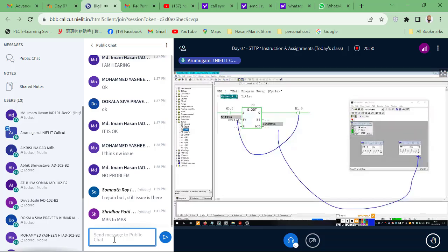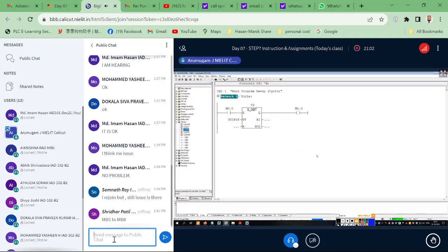We have to add one switch here. Here you see, assign a normally closed switch. That address is this address you have to assign. That's all. That means it will continuously do it. Go offline. I will give the normally closed switch for this location, that address M1.0. Okay, save the project. Then download and monitor.